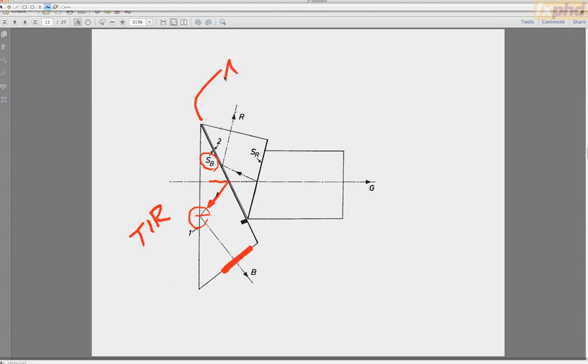Here there happens to be an air gap, and that's a very precise gap. The filter that separates red is here, so there's a dichroic coated on this side of this prism. Total internal reflection is used here, and the red sensor is cemented to this part.